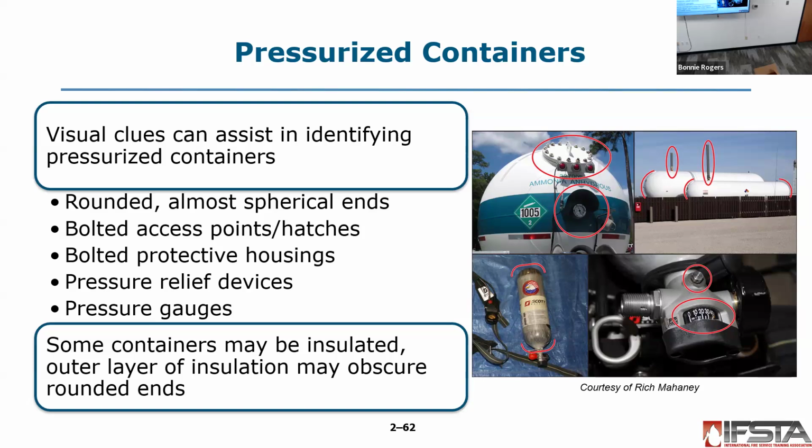Not on fire, I just have a spill. What do I need to do? Start evacuation. Isolate the leak area for at least 100 meters or 330 feet in all directions. What else do we need? You said it's not on fire. Not on fire. Medium pressure, measure distance in the downwind direction.